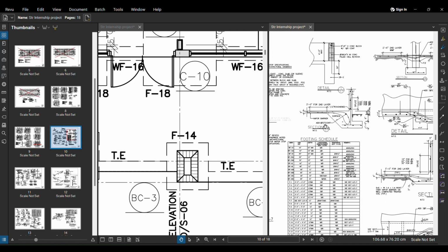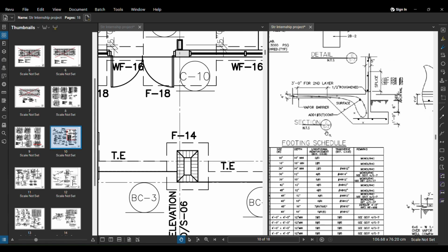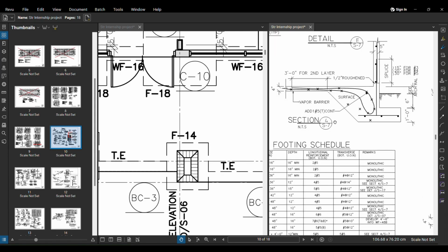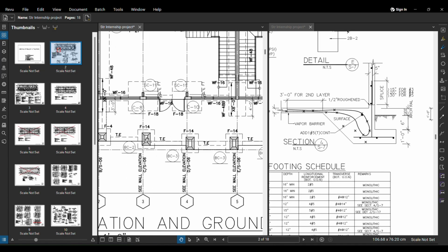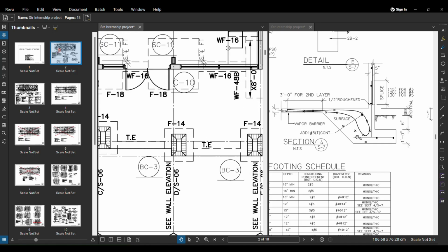Can I see the section 4? Right, yes, I can see section 4. So this sort of footing is not an isolated footing. It is a footing that merges into the slab. Can you see here, on the inside we have a slab, right? This slab goes like this, so this sort of footing merges into the slab, sort of monolithic slab here, and this just blends into our isolated footing.